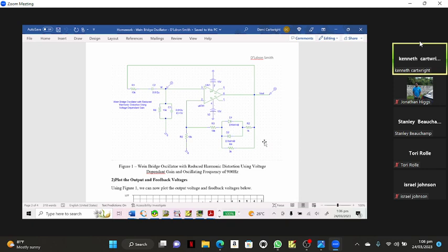You know that much from 230. So let's assume D1 and D2 are off. Okay, RF is 21K. Everybody see that? If D1 and D2 are off, then they're open, and if D1 and D2 are open, R2 is not connected to the circuit.